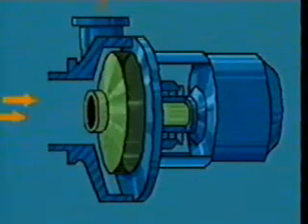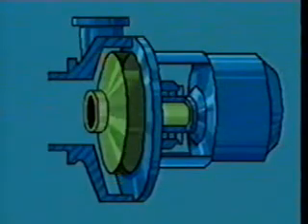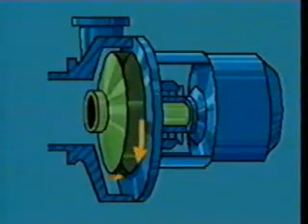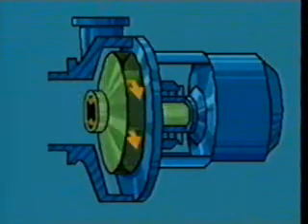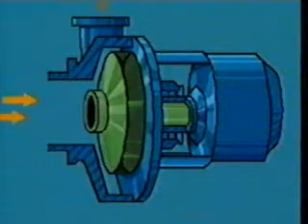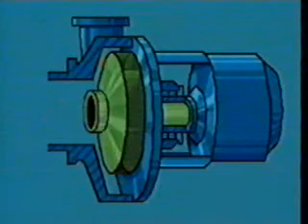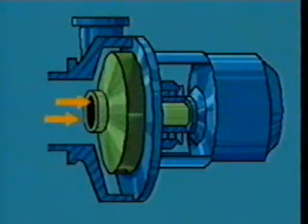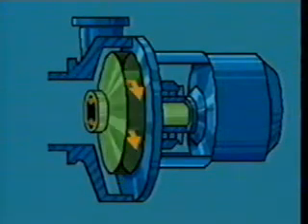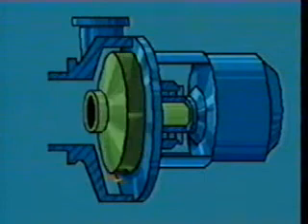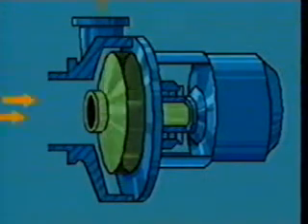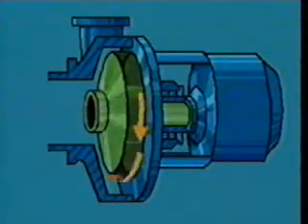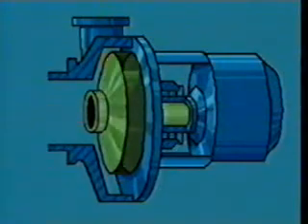Pumps also come in stages, single or multiple. A single-stage pump will work fine for many applications and will raise pressure sufficiently. But there are times where more discharge pressure is needed. It's possible to raise that pressure by increasing the rotation speed of the impeller or by increasing the impeller size. But that's not generally done because of design and material limitations.